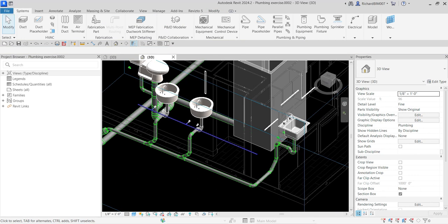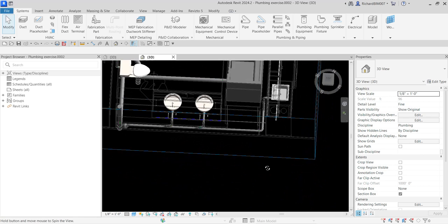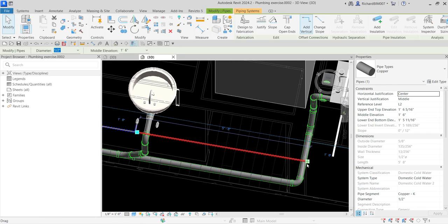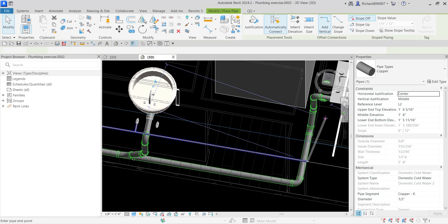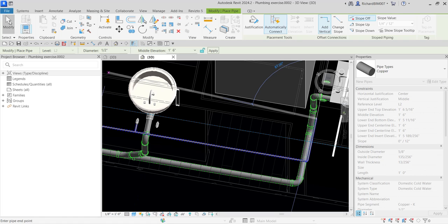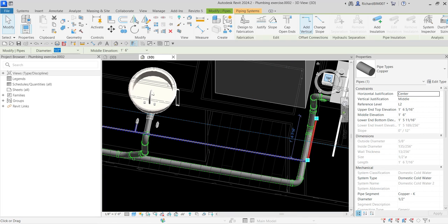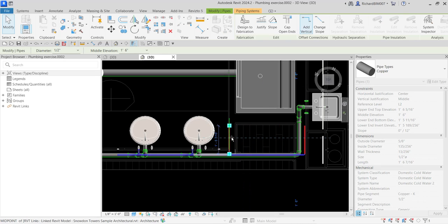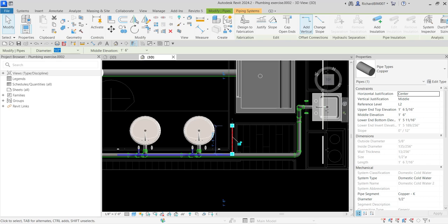Right, now the next thing that I'm going to do is create another series of pipe. So maybe for this one I want another pipe. So I'm going to select this, right click, draw pipe. Okay, this direction here, click, and then modify. So I'm going to click that and then go to the top view, and then let's say I want that to be in this wall here. So I'm going to drag that in that wall. There you go.